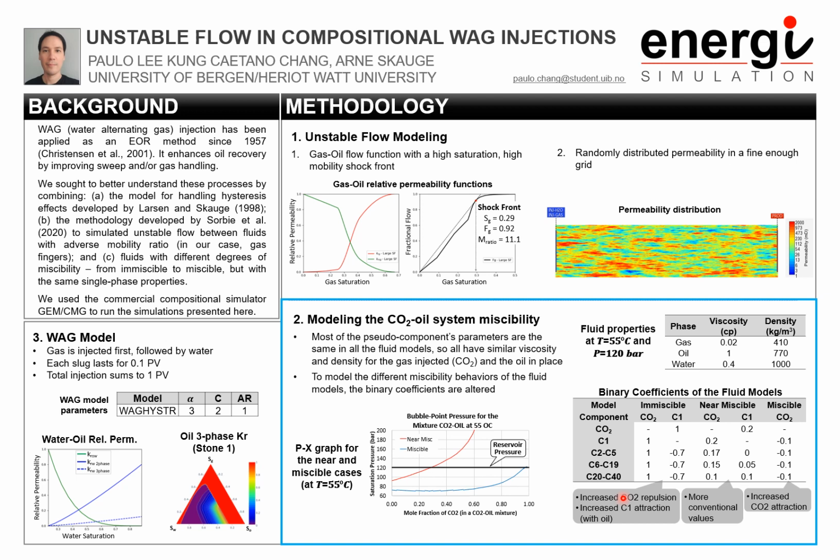or reducing its miscibility. At the same time, we had to use a very negative value for the C1 binary coefficient between C1 and the other oil components to avoid the C1 going to the gas phase when the phases are split, and so obtaining an immiscible fluid where the CO2 never mixes up or vaporizes the oil components.